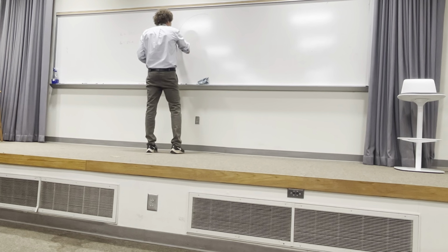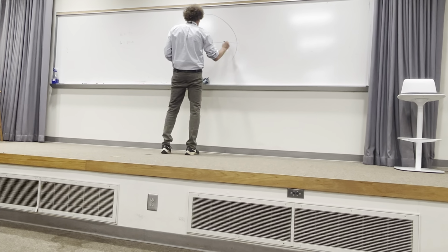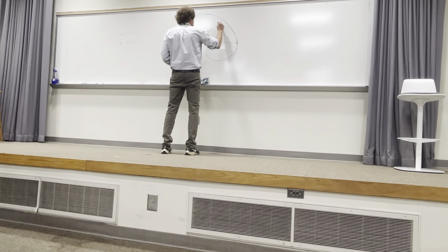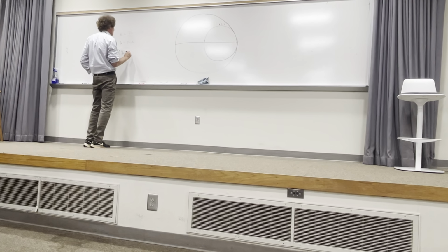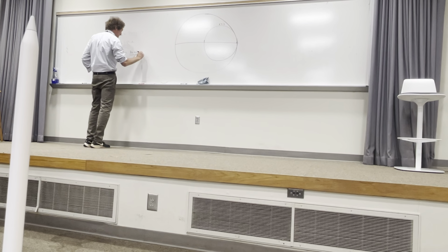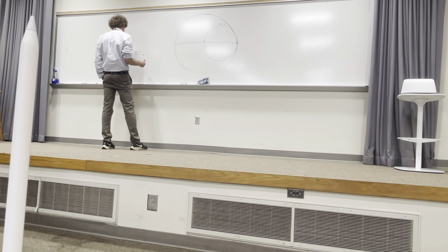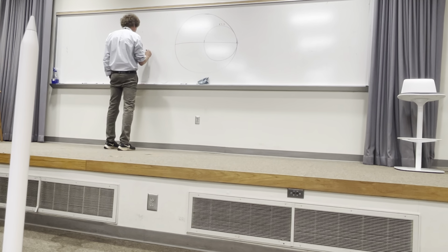So here's the Smith chart, my Smith chart. Now we start by just finding the normalized load impedance, which is going to be 70 plus j110 over 50, right? So what is that? About 1.4 plus j2.2. All right.